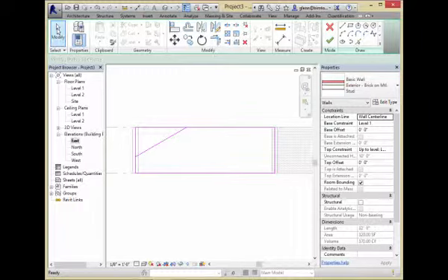Now for all these boundaries, the important issue is that it's going to create positive geometry in the enclosed boundary of the region. And by the boundary, it likes a closed loop. It doesn't like any intersections. It doesn't like any overhangs. It doesn't like things that stop short. It really needs to be an enclosed loop. So this is pretty good as an enclosed loop, but there's some extra stuff hanging out over here. So we want to get rid of the excess.